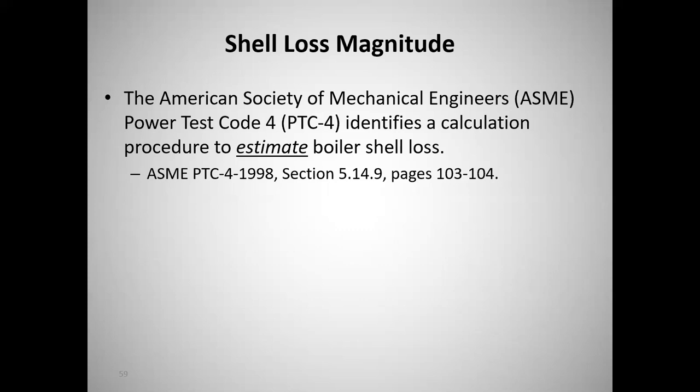So I can shoot this side, that side, the front end, the back end, the top, and usually you just kind of let the bottom go because you can't really get to it. And so you can run those calculations, and you can actually get a hard number, as good as your convection coefficient is, which, you know, those things are always a little bit squirrely. So that's one way to do it.